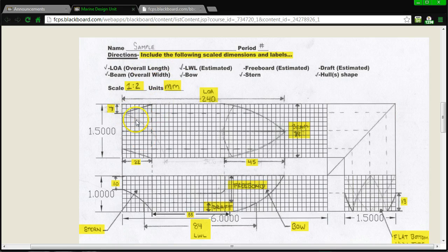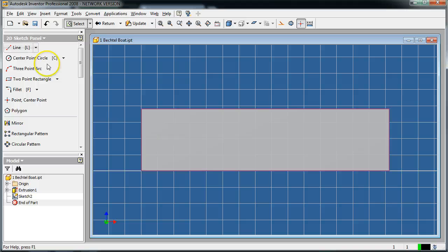So let's go ahead and draw a mirror line, or also known as a center line, and we will then be able to recreate the dimensions that we see on the rough sketch paper. So let's go back into Inventor and draw the line. So turn on the line tool, hit the center line, and find the midpoint. Once the midpoint has been found, go to the other midpoint. Just like in SketchUp, you find the midpoint and it highlights in green. There is my center line. In order to turn off the style of line, I need to click the center line again, and now I will get a nice broad line anytime I make a new line.